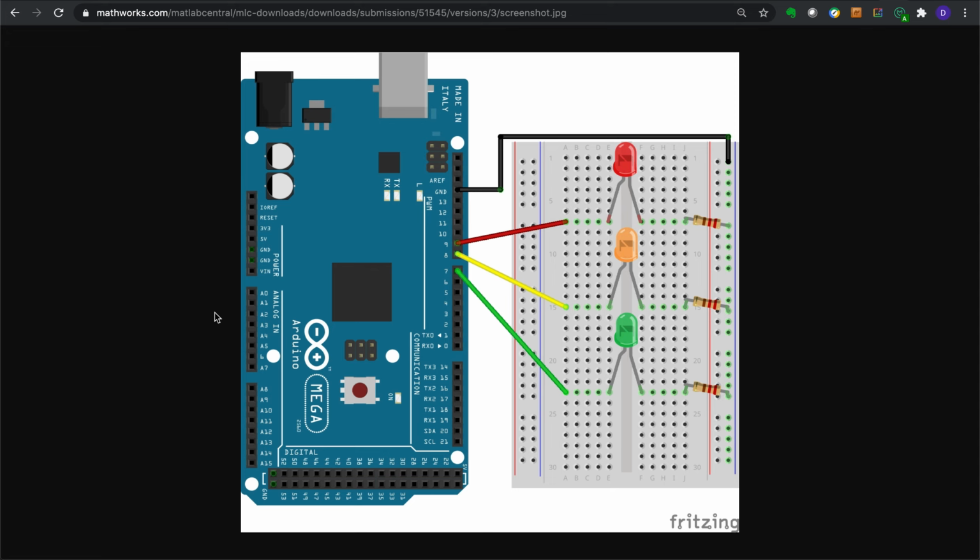You're going to use your Arduino Omega or Uno and make the connections. What you're going to do is drive 3 outputs, one for the red light, the yellow or orange light, and the green light, and make sure you have your resistors in there. We had some students in the past forget that, and they burn things out. So let's not do that. That is the very easy setup, and you're provided all this in your parts kit. So this should be a fun project to do.